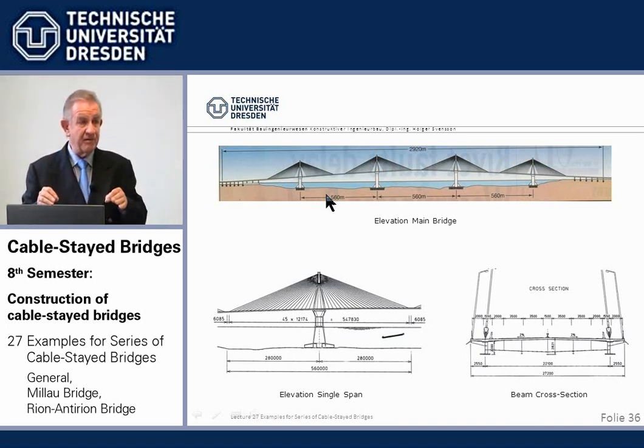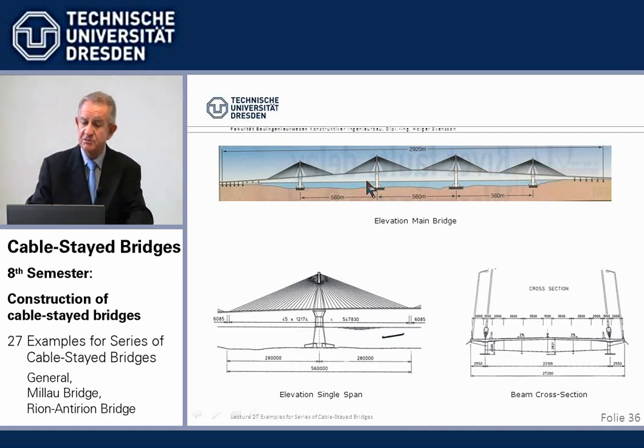Millau, they were very high. Okay, cost money. But with sliding forms or jumping forms, it's not so bad. But here, we had to make them fit against the earthquake, which made them per unit even more expensive in relation. And the more expensive the piers become, the more overall economic it is to make the spans longer. I think that's a very basic issue.